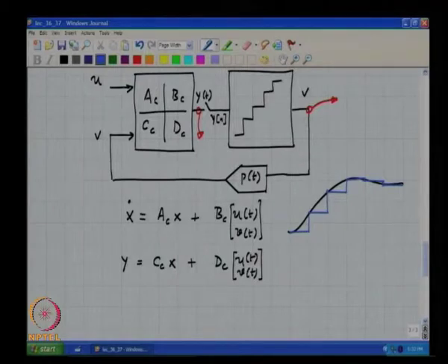Okay. So, as far as the input is concerned, because it is slowly varying, since we are dealing with an oversampled converter, one can think of it as a sampled version u of n driving the pulse shape, which is actually an NRZ pulse, correct. Therefore, if this pulse is also an NRZ pulse,